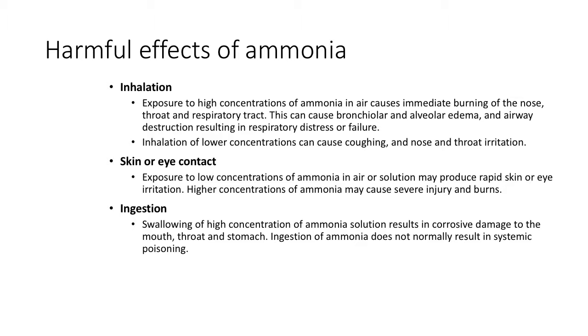For skin or eye contact, exposure to low concentrations of ammonia in air or solution may produce rapid skin or eye irritation, while higher concentration of ammonia may cause severe injury and burns. Lastly, swallowing high concentration of ammonia solution results in corrosive damage to the mouth, throat, and stomach. Ingestion of ammonia does not normally result in systemic poisoning.